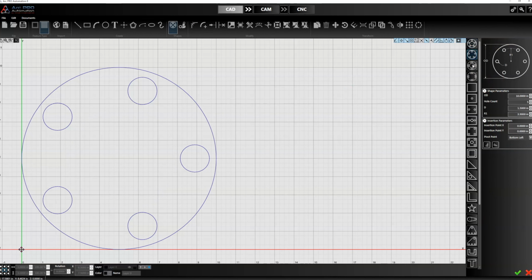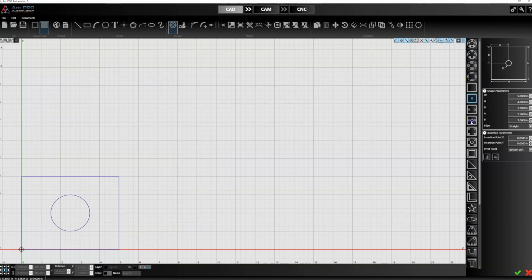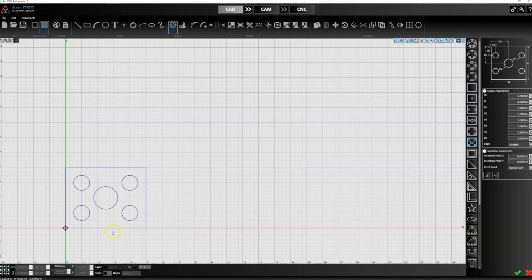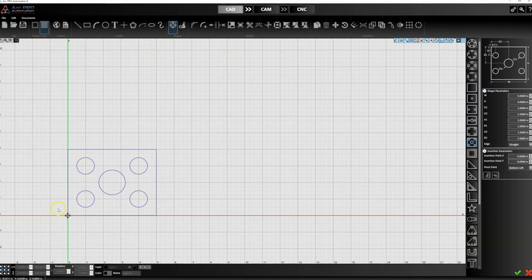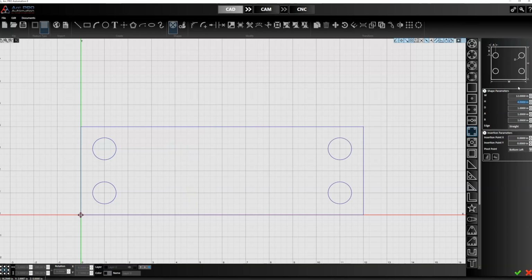You'll see all these different flanges. There's circle flanges, slotted flanges, square plates, all kinds of options here. And what you'll notice is that when you select one of these, for instance, we'll select this square, and let's just zoom in here, bring it to the center of the screen. Say you're making something like a base plate to weld a post to, and say that base plate is 12 inches by 12 inches, you can just go to the right hand side menu, and notice when I add 12 inches into this field and click Tab, it automatically shows the difference in the part.